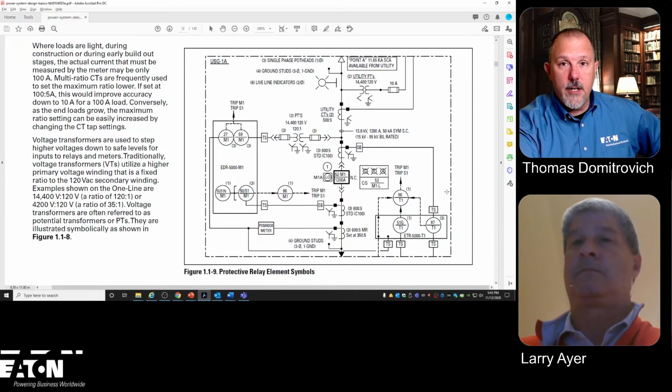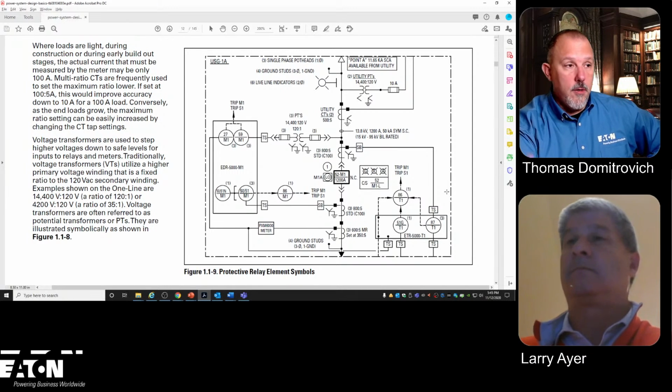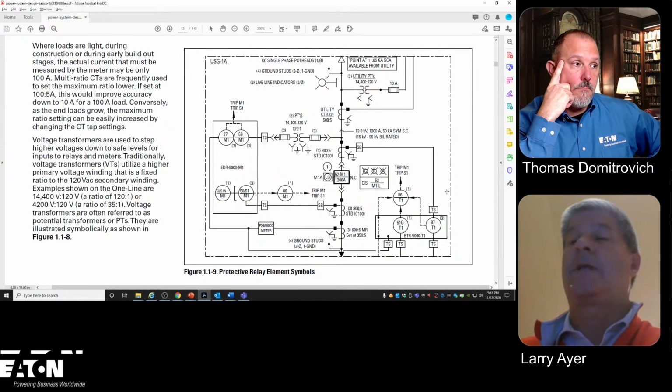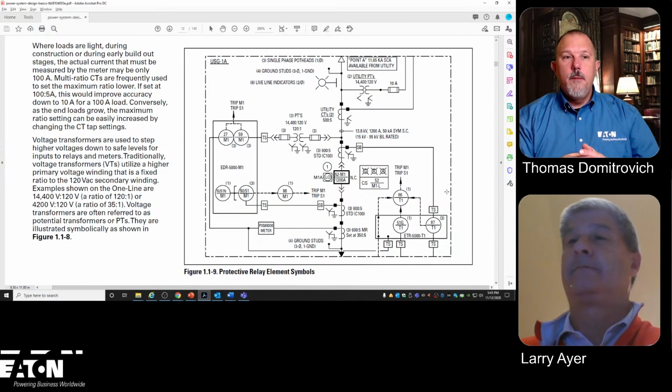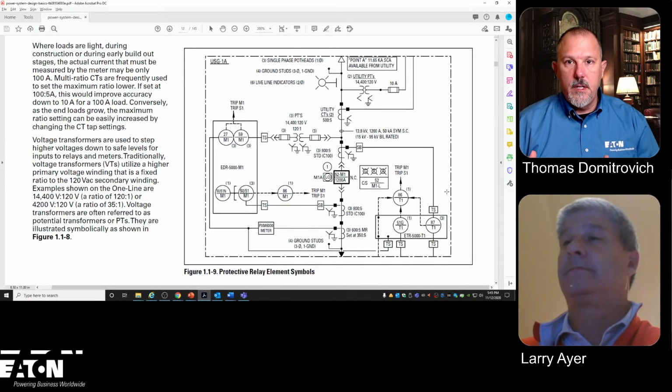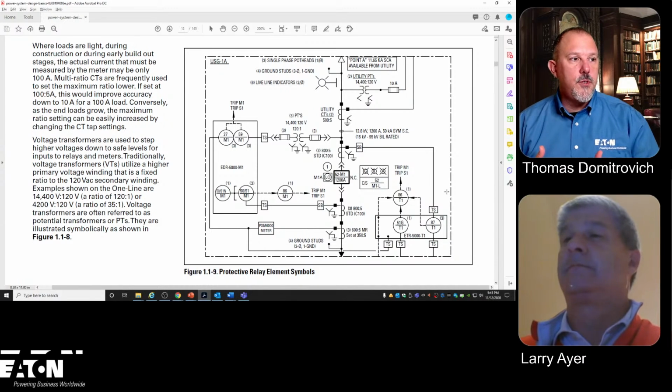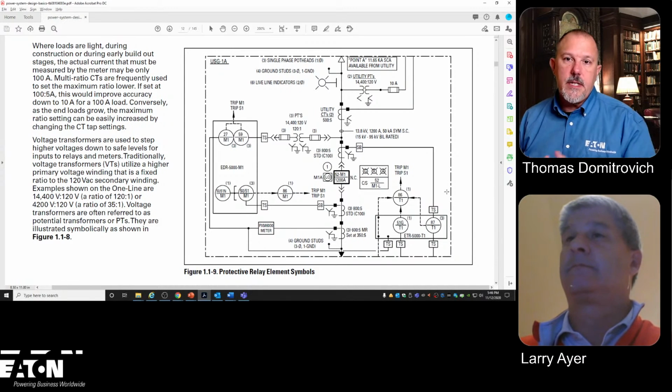You're not looking at a handle rating on a circuit breaker. You're looking at relay set points with long time pickup and comparing that with conductor ampacity values. That's correct. And they would typically not get into CTs because that's all part of the equipment, but they would have to be able to understand the relays and whatnot that are providing the protection.